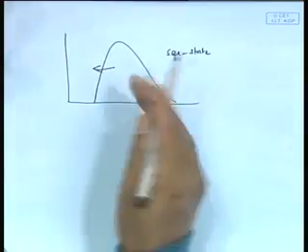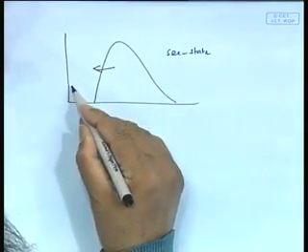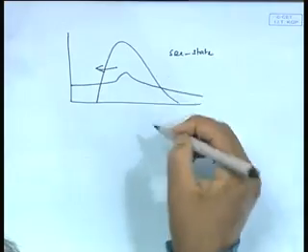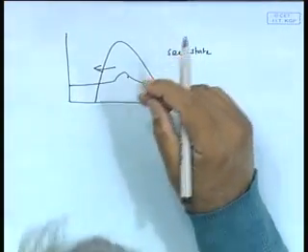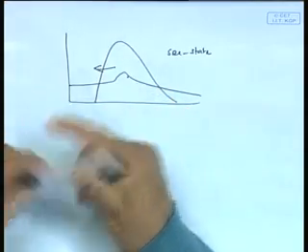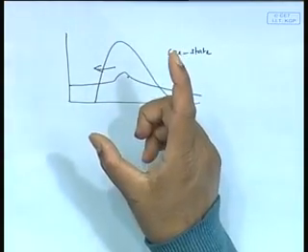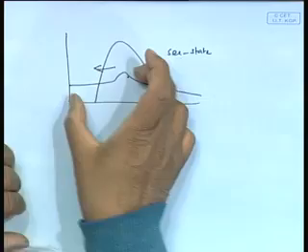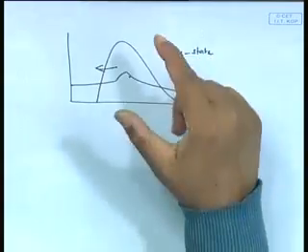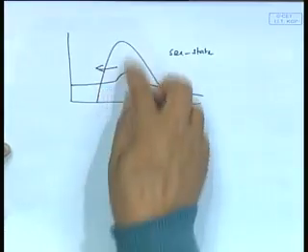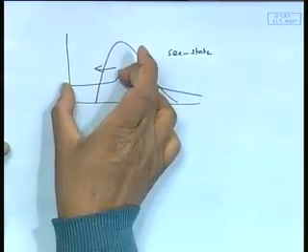Now, if I have a particular barge like that, this does not change, but the sea state shifts to this side. So, you see, in fact, this explains why typically small boats respond very badly in low sea state, because in low sea state the spectrum is at this side and the peaks are maybe 6-7 seconds, and small boats, because AWP is small, etc., also have a smaller typical natural period. So, it is on this side, but if you shift this side, what would happen?